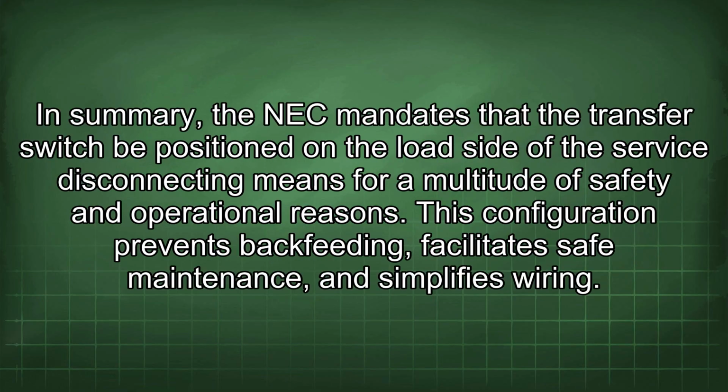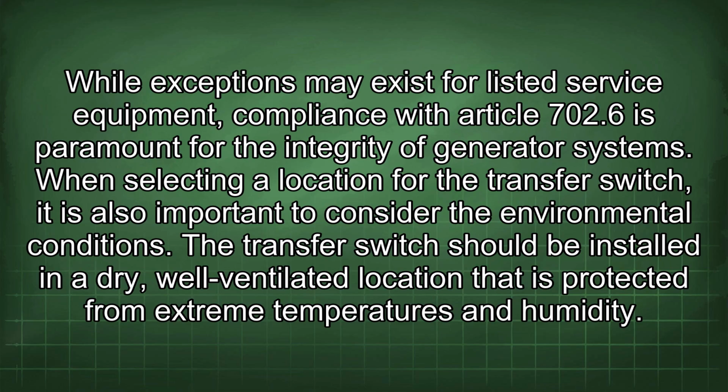In summary, the NEC mandates that the transfer switch be positioned on the load side of the service disconnecting means for a multitude of safety and operational reasons. This configuration prevents backfeeding, facilitates safe maintenance, and simplifies wiring. While exceptions may exist for listed service equipment, compliance with Article 702.6 is paramount for the integrity of generator systems.